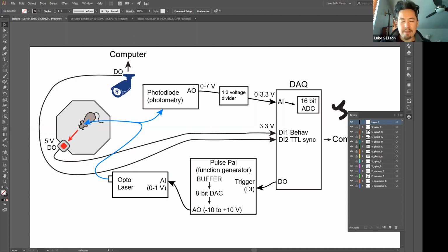So that's one thing: if this is an expensive laser, you have to think very carefully about this. You know, because there's also situations where, for example, say that you reboot this function generator or whatever. Sometimes when you reboot it, it transiently drops to -10 and then +10 before it goes back to 0 or something like that. And I've seen stuff like that happen. And so you have to think about all this stuff.